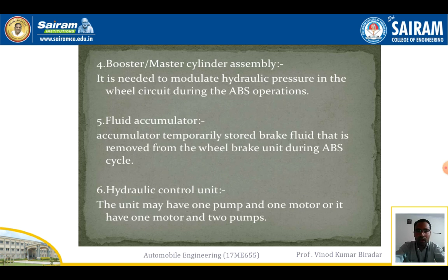Next, the hydraulic control unit. Normally the hydraulic control unit is connected with an electronic control unit. This unit has one motor and two pumps to supply the fluid from the master cylinder to the hydraulic control unit, and from the hydraulic control unit to each of the four wheels.